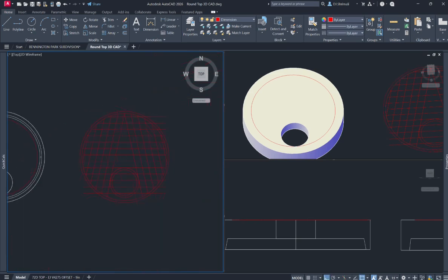So I'm going to trim all those rebars so that they are within that 2-inch cover. Showing cover is important, so that when production sees those rebars, they know that they need to maintain a certain cover. And in round tops, we usually use a circumferential wire, so that 2-inch offset circle that you see, that's where we will put the circumferential wire. So it's like a vertical wire mesh that you wrap around, and in that wire mesh you place your rebars.